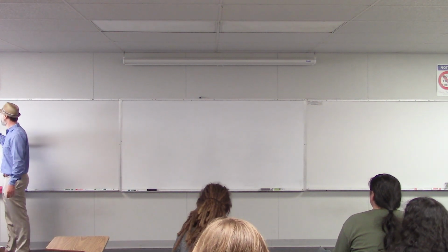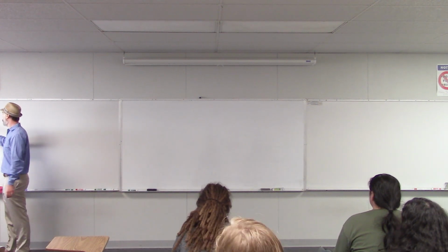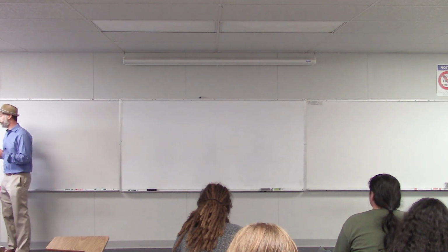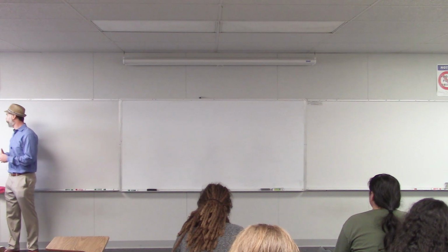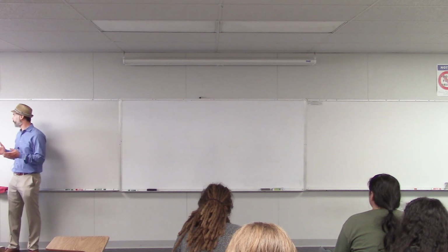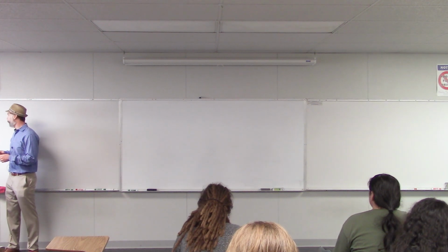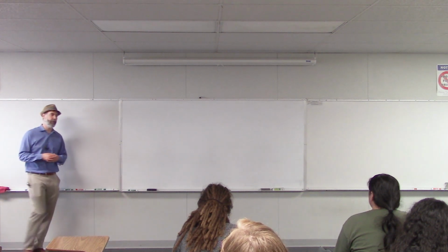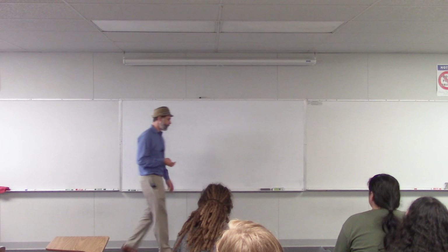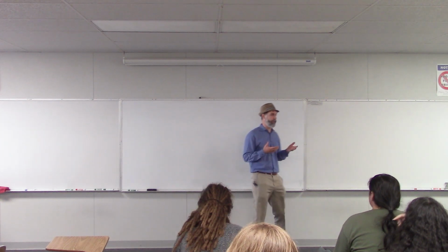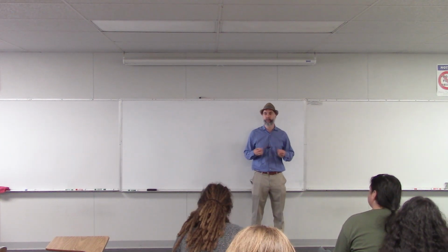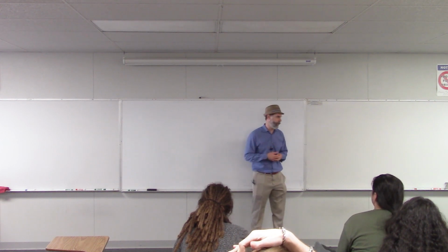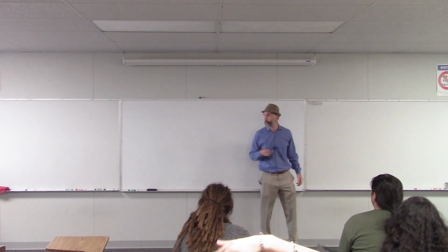So basically, for soldering, there are 2 key things that you want to keep track of. There are 2 things that you want to strive for. You want to be clean when you're doing your work, and you want to have enough heat when you're doing your work. So if you can achieve those 2 things, then you should have a good solder joint. So let me talk a little bit about those.